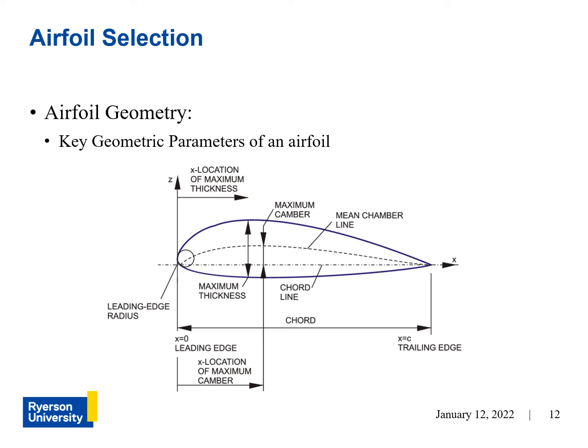The proper reference axis for an airfoil starts at the leading edge and goes to the trailing edge. Now, it's not obvious where the leading edge point is for most airfoils, so the rule of thumb is that the leading edge point is just the furthest point from the trailing edge point.